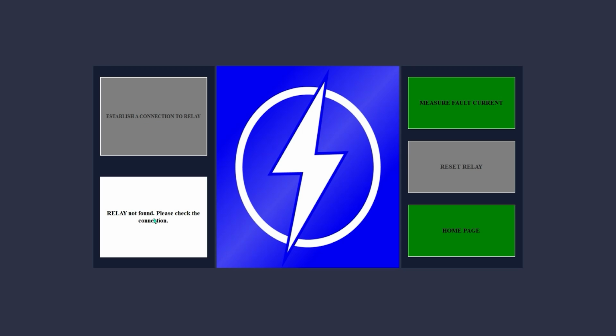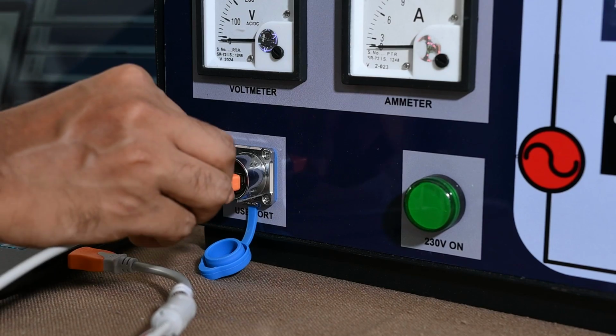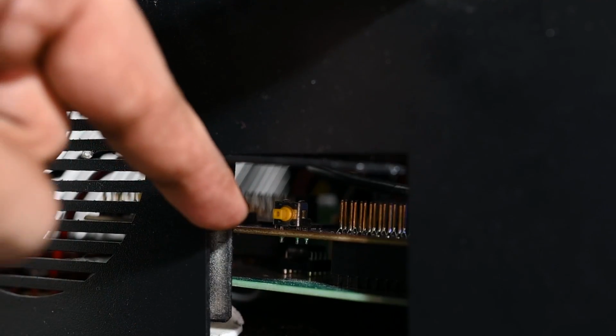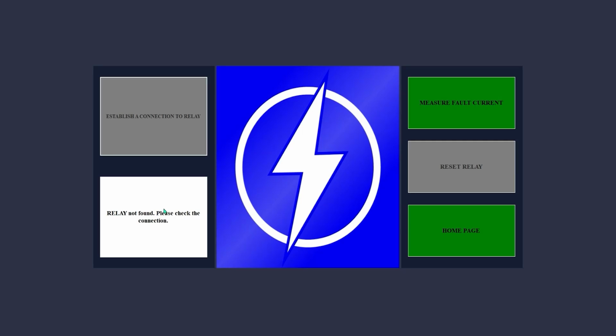A message like "relay not found, please check the connection" may appear. If you see this message, it means the system is unable to detect the relay hardware. This usually happens due to one of the following reasons. First of all, the USB cable is not connected, or the reset pin on the relay kit is not pressed. Ensure the USB cable is properly connected. Then press the reset pin on the hardware to initiate communication. Now I verify the USB connection, but the establish connection button is still inactive.